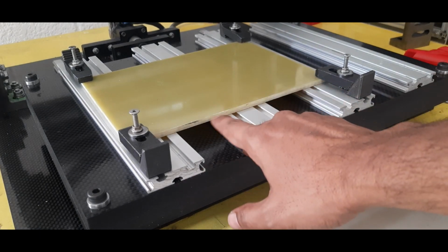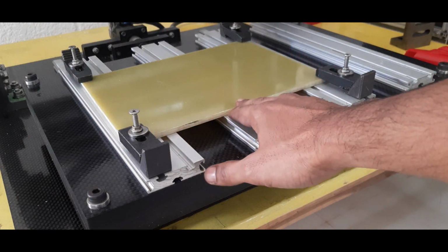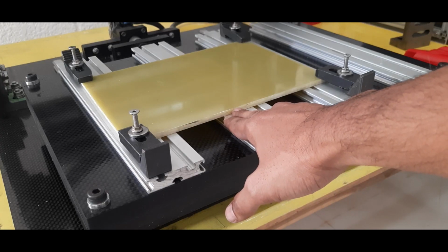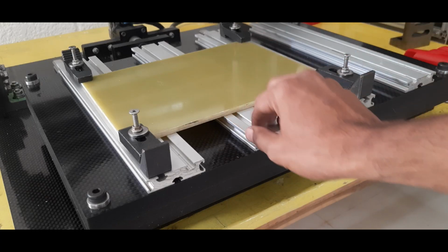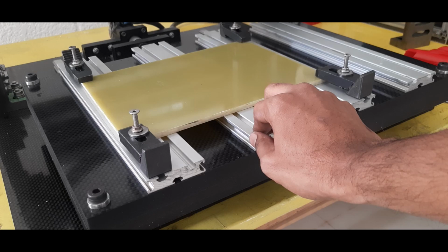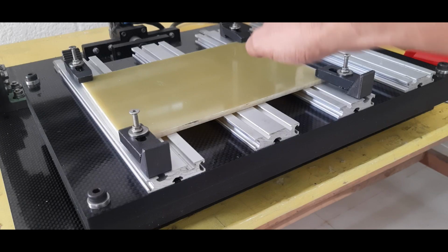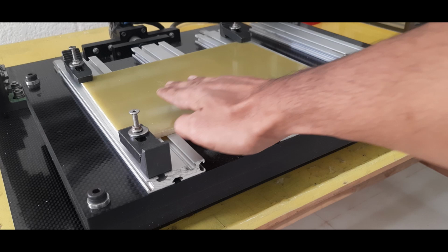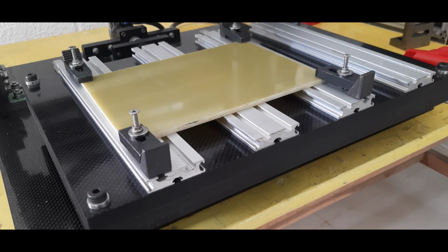Now that we've installed the wasteboard and clamped it to the surface, with the double-sided sticky tape for additional security, it's still not flat. This surface cannot be guaranteed to be flat because we are engraving PCBs with tolerances of 20 and 30 microns. We need to first face this surface with respect to the spindle, and that is what I'm going to do next. I'm going to use a 10 mm flat end mill and mill this surface, onto which we can then mount our PCB copper clad board.